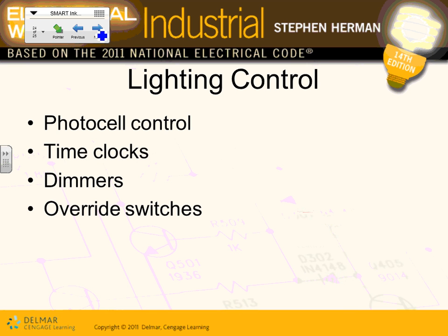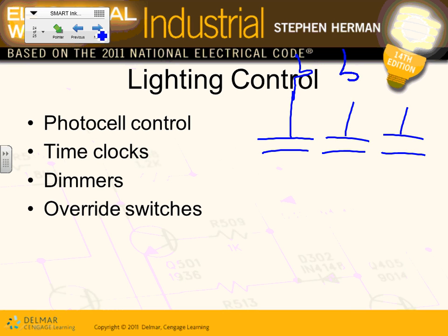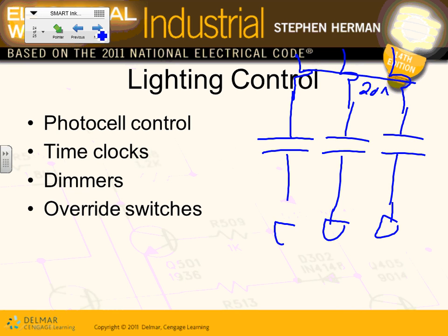Lighting control, like we said: when you have your 1, 2, 3, and I'm doing 3-phase here, here's my 3-phase. These are 20 amp going to multiple sets of lights, here's one set, one set, one set, and from this side you take the neutral.